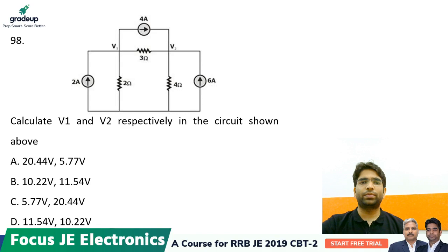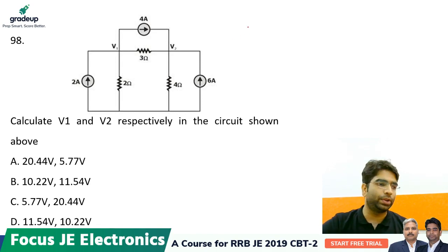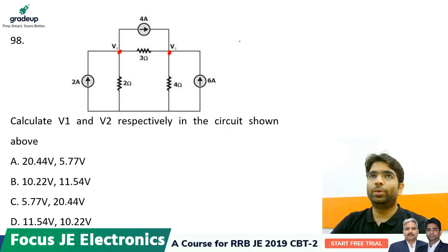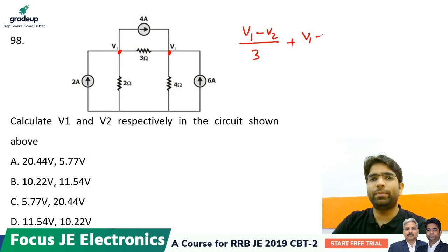Look at this question. It is from nodal analysis. If you proceed with nodal analysis, it will be very easy. Take this as node V1 and this as node V2. Now apply nodal analysis. The reference node is this. V1 minus V2 by 3 plus V1 minus 0 by 2.